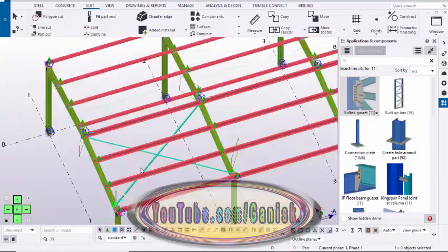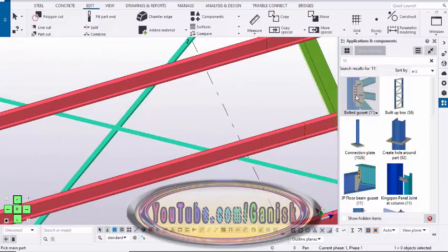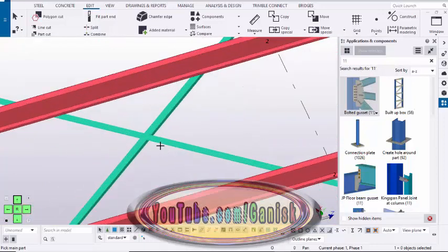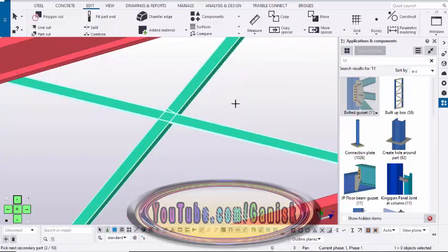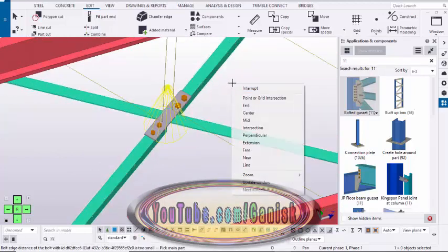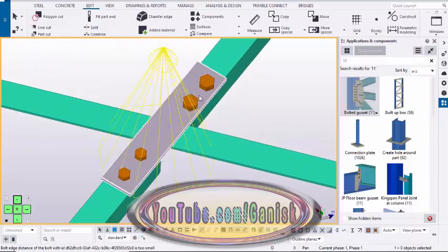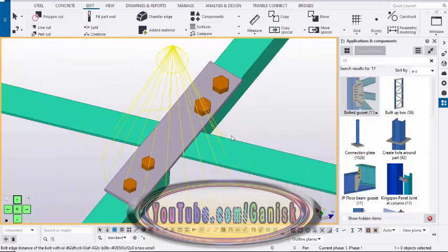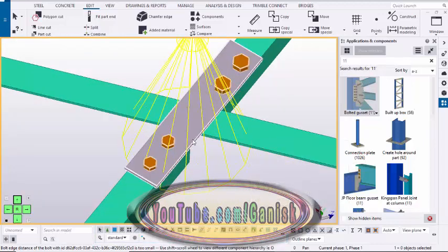Now we're going to give the connections between this angle to angle. So select this brace bolt 11 and select the full length angle, and then select this remaining 2 angles and press the scroll wheel button to place the angle like this. Click on space, right click on mouse, redraw. Now we need to change the bolt sizes in this direction at here. Okay, select this option, select component, and then double click on this connection.